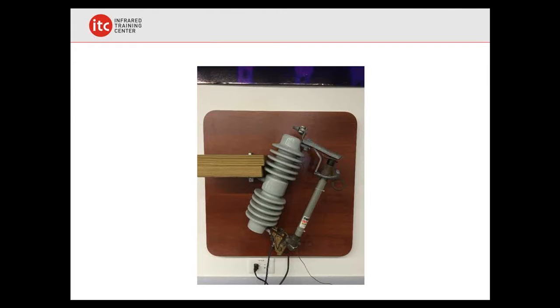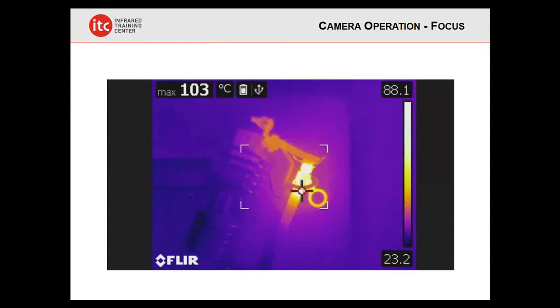We use this as one of the targets during our infrared training classes, and I use it to demonstrate the importance of focus on adjustment of the image. I don't know if that's going to load here. I don't think it's loading. Unfortunately, I don't think it's coming up, but as Maureen said, we do have technical issues sometimes. But the important point here is that if you're out of focus, your temperatures are out of focus. They will not register as clearly as they should. And so proper focus is essential for getting good images with infrared.